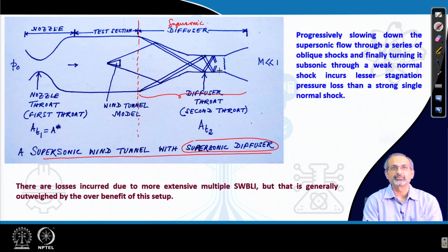It is going to accept the supersonic flow, send it through a converging section, then send it through a constant area section and then a diverging section. As it does so, what happens? The shock from the model, and additional shocks which are created from the lip of the converging section, reach the walls and bounce back, and multiple reflections are caused, but the flow is gradually slowing down, because as the flow crosses each shock, it is reducing in terms of Mach number.